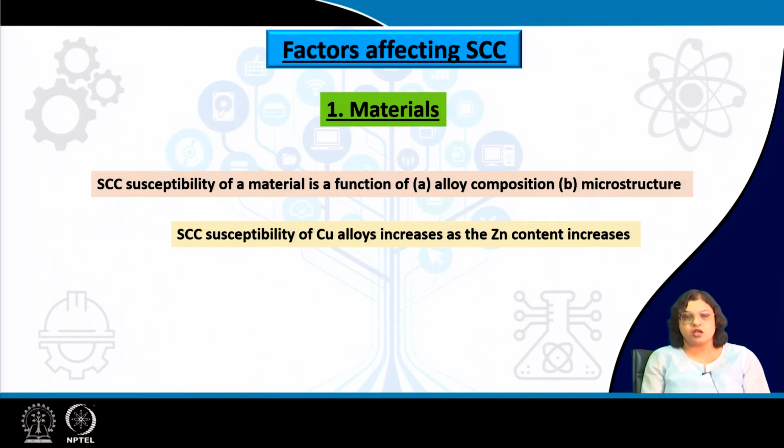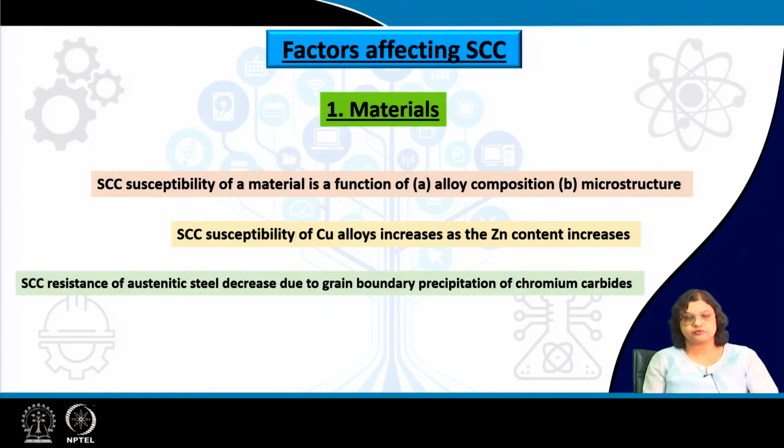during service. So, it is known that the SCC, or stress corrosion cracking, susceptibility of copper alloy is particularly related to the zinc content. If the zinc content increases, that may make the copper more prone to undergo stress corrosion cracking.